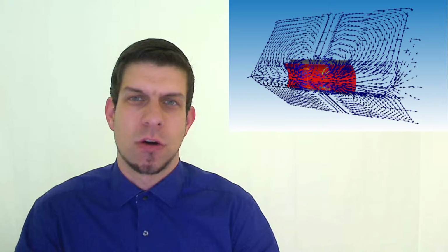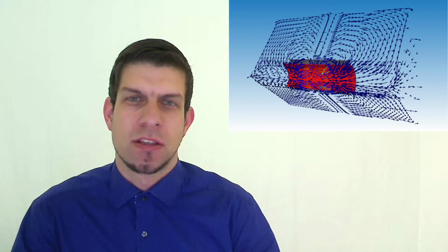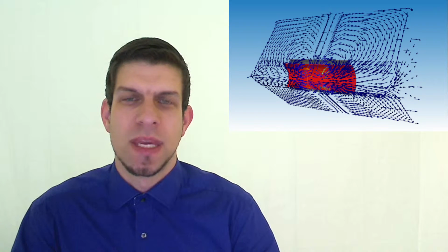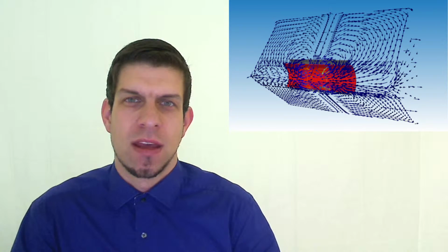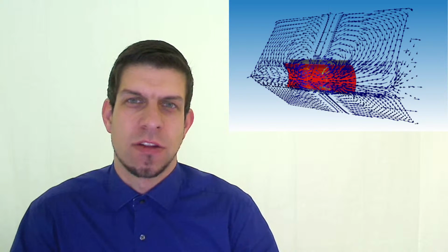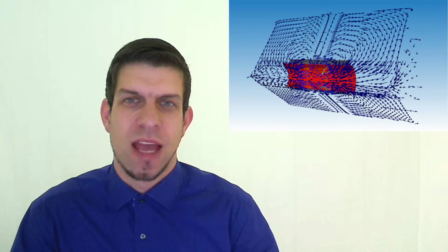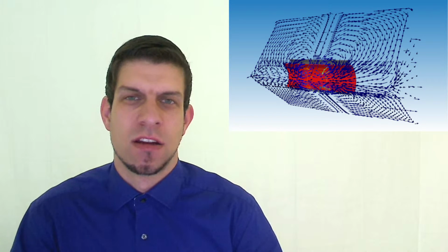Then in the magnetic domain we have introduced support for Biot-Savart coils. So with Biot-Savart coils you can describe the current coil piecewise by line segments. And the very interesting thing is that this is not a method bound to your mesh, so that is, you just describe it via certain coordinate locations, and this means it's much easier to place some coils or also coil variations in your existing computational domain.